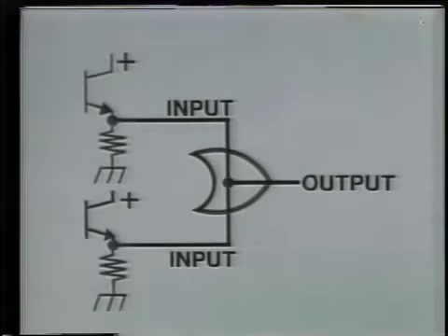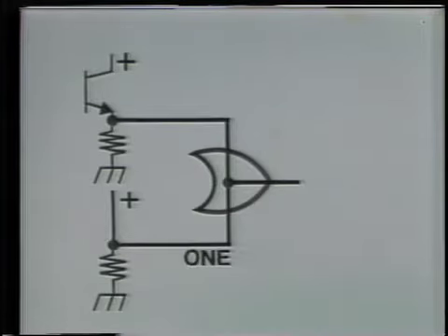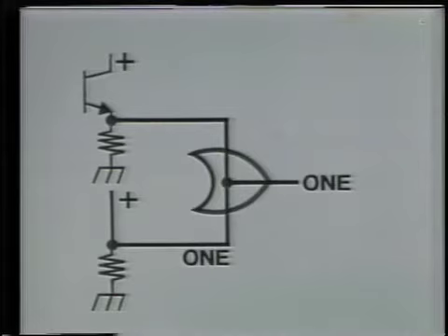If we use a pair of emitter-follower NPN transistors and tie the 2 emitters together at the output, we would find that this circuit would perform the logic OR function. If the driving circuit tries to force a 1 on either or both inputs, the output will be a 1. Again, it is very important to note that when 2 wires are connected like this and used to perform a logic function, the driving circuitry is what determines whether the function is a logic AND or a logic OR.